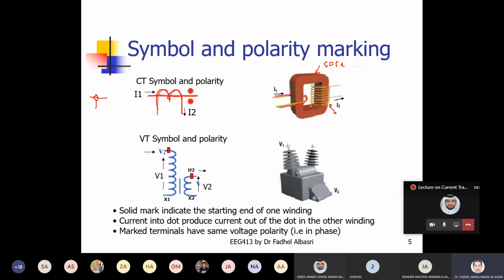All right. So this is primitively a transformer. This is a current transformer, same as other transformers, except the primary is not multiple turns here. It's just a single turn mostly. But we have some CTs where we have more primary turns. The secondary can be either one or several. Have some taps here, so that you can have multiple ratios.